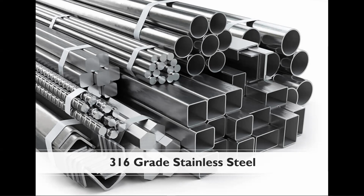And grade 316 stainless steel in general is an austenitic stainless steel with the benefits of higher resistance to pitting and crevice corrosion in chlorinated environments, with excellent toughness characteristics due to this austenitic microstructure. So given the characteristics of this material, typical applications can be found in things like food preparation equipment, boat fittings, lab benches and equipment, as well as bearings for medical devices, due to each application needing some form of corrosion resistance and high toughness.